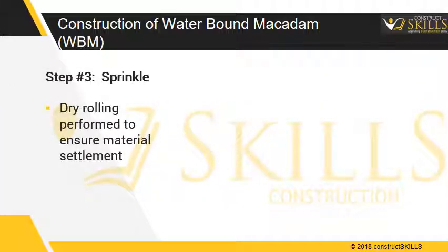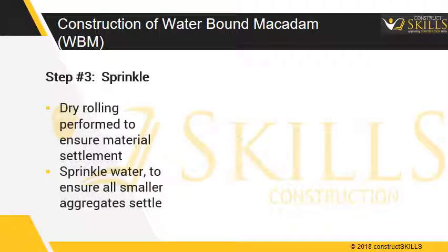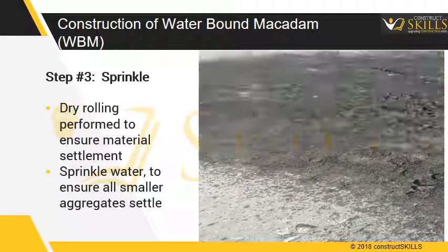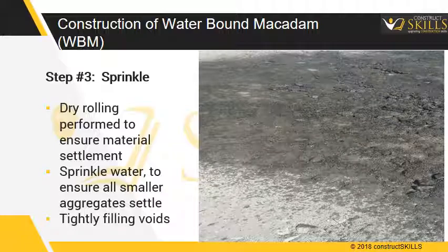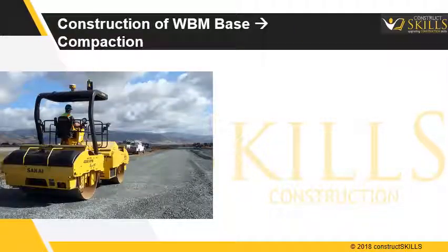Dry rolling should be performed to ensure all material is settled. Only after all the screening material is settled, and voids filled, sprinkle water, to ensure all the smaller aggregates settle, tightly filling the voids.